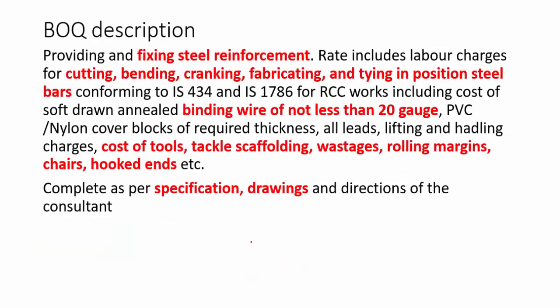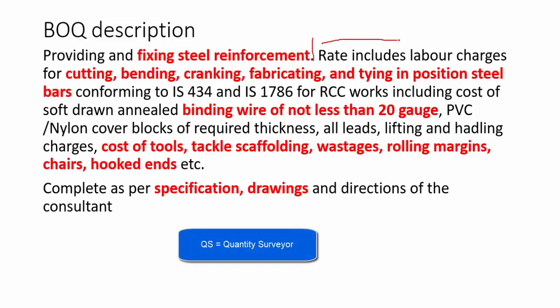Okay, then the next step is the BOQ description. What does the QS need to know, what are the points that are important to highlight. That is, I will read for you: providing and fixing steel reinforcement. Rate includes. So this is most important for the QS to know. Okay, this is the point where the QS needs to focus more, because all the rates relating to estimating, the QS is the one who is responsible.